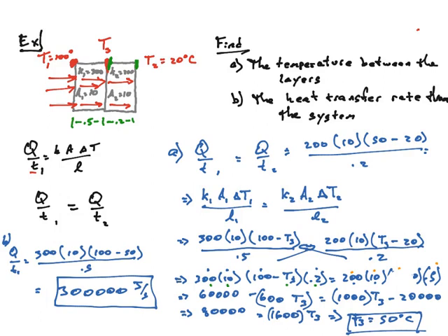First thing you should do is calculate the temperature in the middle, at the interface between the 2 materials. Call it T3 or call it T middle, whatever you want to name that value. I usually call it T3, but that's just my own thing I've been doing since I was a student. So first you calculate that.